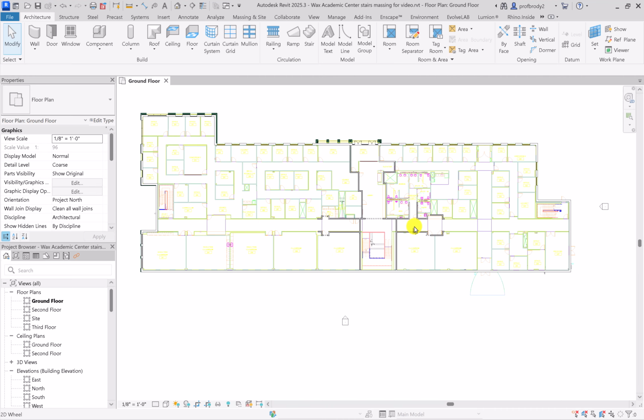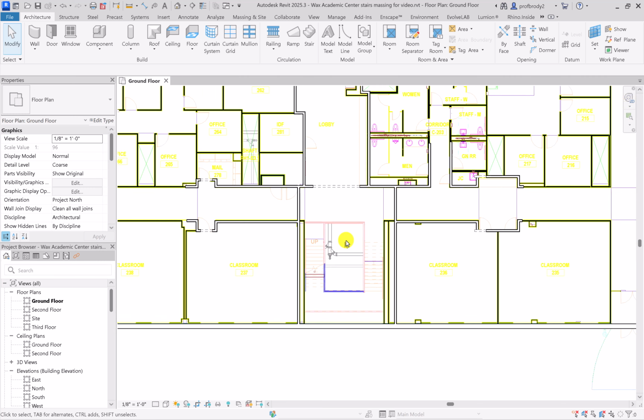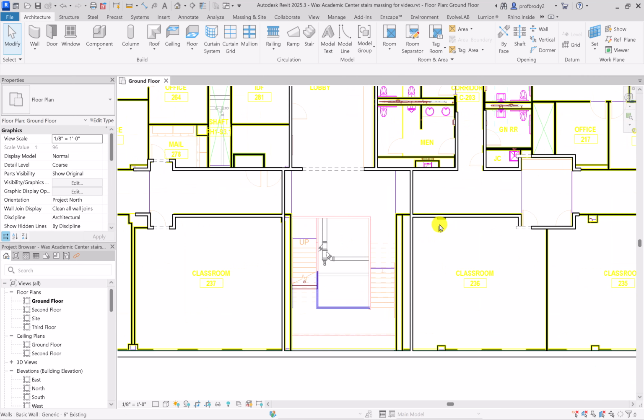So here's the existing conditions building that we created, along with a selection of interior walls. There's an existing stair here right now that we are going to replace with a more dramatic stair. The place to start is to hide all the stuff you don't want to see, create the atrium space using multi-height walls, and then any of the corridors which repeat on each level will be walls which are just created on, say, level 1 and copied and pasted up to multiple levels.